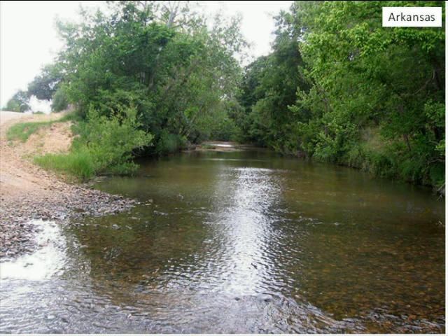Granted, they won't support the same equipment load as the two crossings shown in the previous slide. But fords like this represent a good number of the crossings that NRCS installs. Simple fords offer a good mix of construction ease, stability, safety for livestock and equipment, and generally work well with the stream over time. All of this equates to good passage conditions, good stream function, and minimal maintenance.